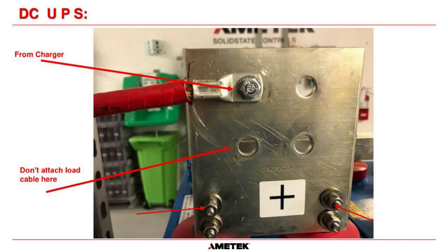So it's much better to follow the design and have the battery go through one breaker to the DC panel and the charger go through another breaker to the DC panel. I hope that was clear. Once again, remember, if you have any questions, just type them in the chat bar on the side and I will go through them as we go.